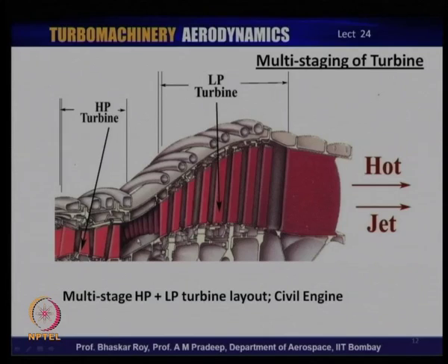And in between, as you can see, there is a large interspool duct or gap, during which, as you can see, the flow has moved from a median radius, which was here, a lower radius, to a higher median radius, and it has continuously moved to a higher mean radius. This of course tells you very quickly that the designer wanted to continuously upgrade the value of U or U mean of each turbine.